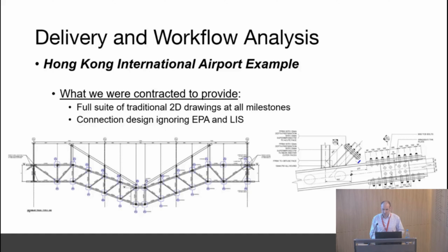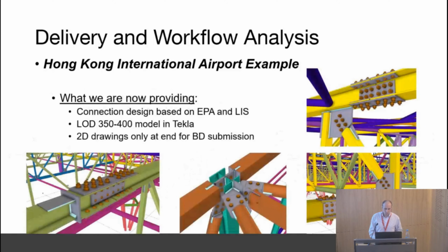So we're lucky on this that we do actually have quite a progressive client, and we've had these discussions with them. So what we're now providing is we are looking at the erection phase analysis based on some of the more credible methods of building it. We're including the locked-in stresses, we're completing the design, and we're completing pretty much an LOD 400 model, which is a shop model with everything except for presets and precambers and shop marks, essentially. And we're only producing 2D drawings once. Unfortunately, yes, we still have to produce 2D drawings because in Hong Kong, they have a pile of drawings that they rubber stamp physically, and that's what they do. But we're not doing that at interim milestones and wasting all that time.